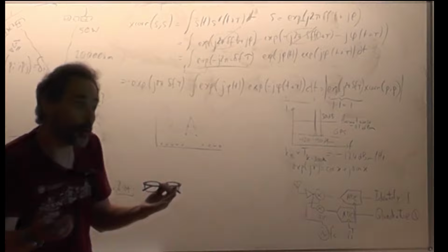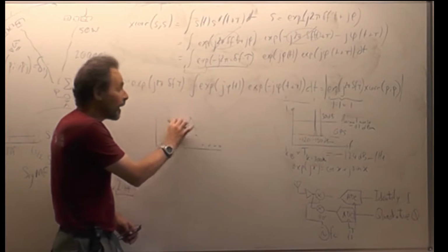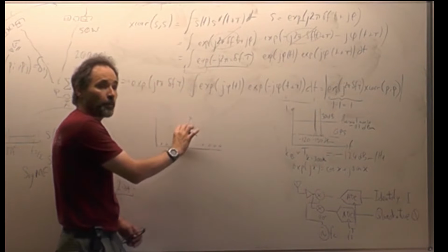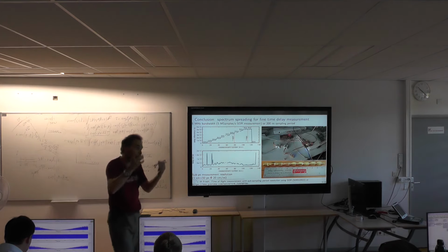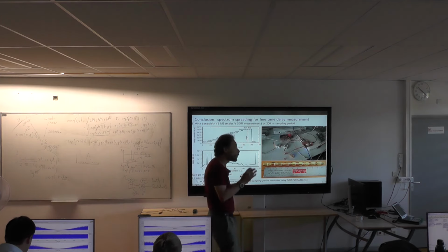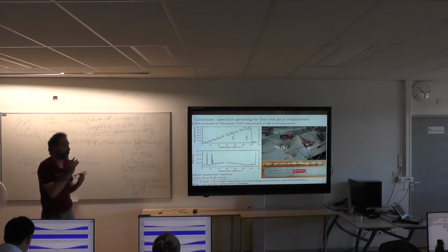And what you can demonstrate is that the improvement in timing capability is proportional to the signal-to-noise ratio. So if you have a high signal-to-noise ratio, and that is the case with communication with a geostationary satellite, you can improve your timing capability beyond the sampling period.